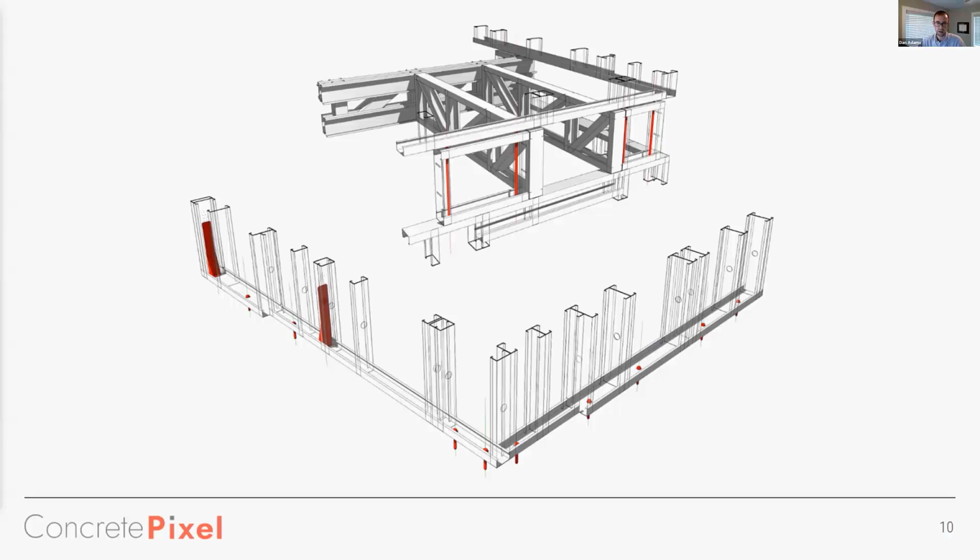Usually the risk of advising on means and methods is where that would come up with anchor bolts, but that's effectively eliminated due to vertical integration. So the exact locations of bolts can be specified. Something like using screw anchors can reduce coordination between slab pours and framing installation. That's typically a pain point with cast in place anchors because they can conflict with vertical studs and door openings. That would be a situation where field modifications would be required, which again slows down construction and could impact the quality of construction.